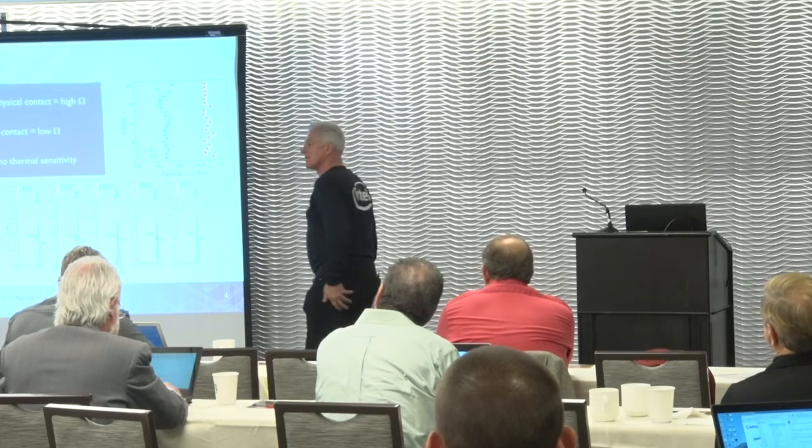It's not something that has to be tuned down at the individual level, because what we're getting out of this is, as we do sets and resets on these cells, we're getting between 10x and 20x resistance change. And that's plenty for us to be able to sense in a reliable way between the set and the reset